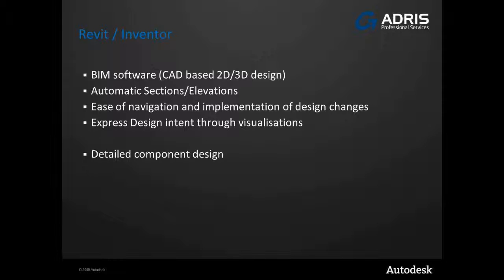Revit also works with the principle of constraints. So you can build in design intent by applying constraints. So you can build in an association between elements within the model, and those elements will behave predictably based upon the constraints that you apply. So in simple terms, you could say that two walls are to line up, and that if one wall was to move, the other wall would move with it. Or, for example, you could define building content, so you could have ductwork, which is a pre-configured distance off of a wall. Should the wall move, the ductwork would move with it. So we have the principle of constraints.